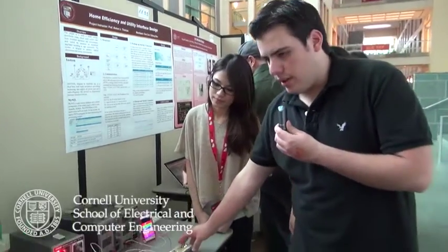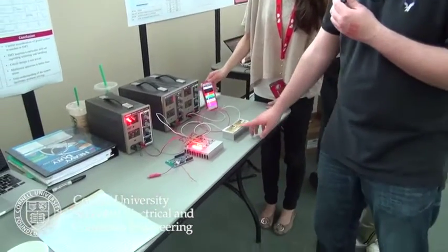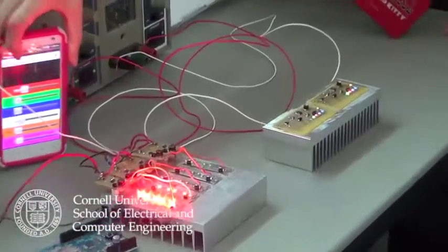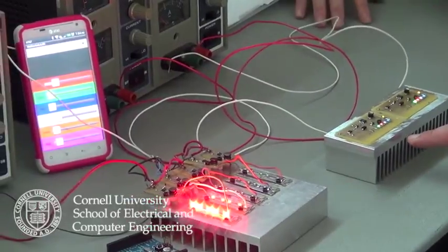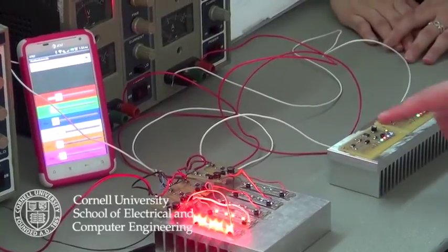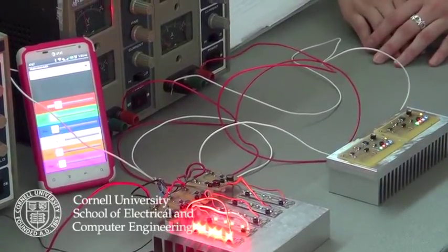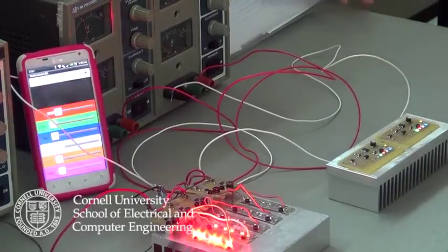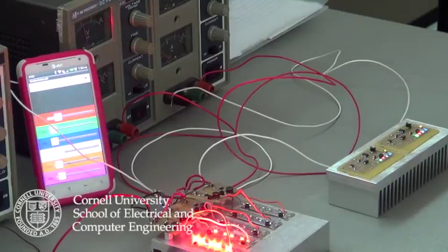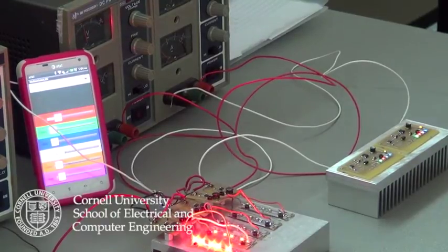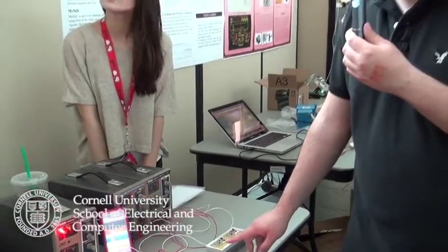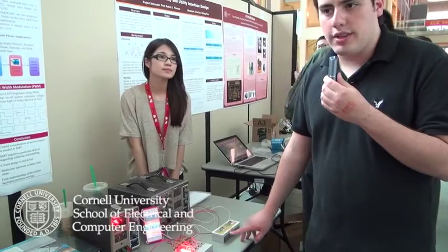So we actually designed this integrated board, which combines 5 different colors to produce a better spectrum of light. These LEDs are very high power. They can produce a lot of light, which I will demonstrate shortly. The circuit itself consists of a control unit which controls the current that goes through, because there is a threshold of optimal operation which goes from 500 to 700 milliamps. If it goes more than that, it can burn the circuit. So what this does is that if the voltage gets increased, then the current gets controlled.